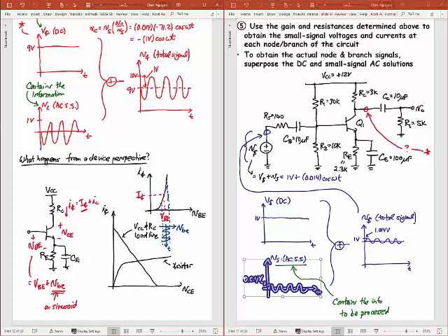What I'm doing with my small signal analysis is I'm approximating this curve by a straight line. Right? That's where my Taylor series expansion comes in. I'm not actually looking at the actual curve, which has some curvature. I'm sticking in a straight line that is the tangent at that point. Right? And so this line has a slope equal to what we derived as gm.